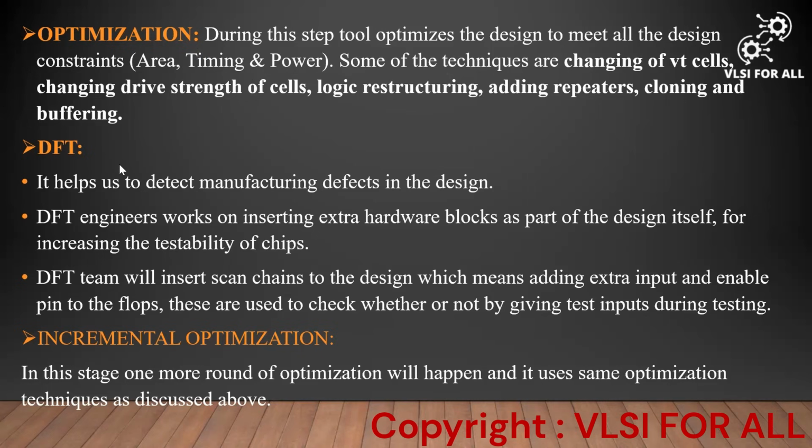So the next stage is DFT, which means design for test. What we do in this DFT stage helps us to detect manufacturing defects in the design. Let's say we have some cells or flops, they may have manufacturing defects. So the DFT team will be separate. They insert some extra hardware logic and provide some files. Upon taking those files and using them, we can check whether any manufacturing defects are present in our design or not.